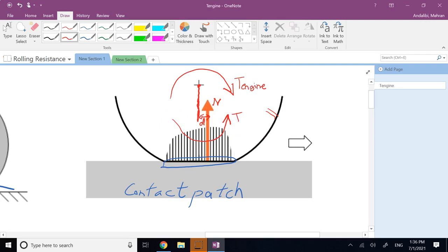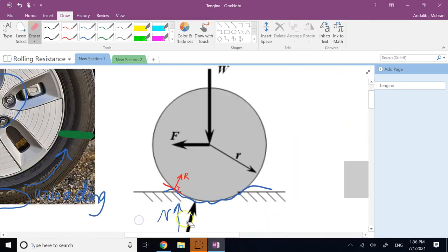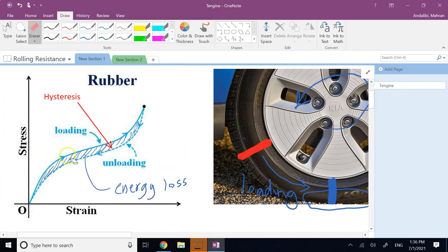This is the T of the rolling resistance, which is equal to N times d. You clearly see this torque is going to oppose the torque applied to the driving tires, and that's another way you can justify the waste in energy, right? It's an opposite torque. So whether you call it opposite torque, you call it opposite force, or you call it hysteresis, the matter of fact is when an object rolls on the floor of any type, there is always a resistance backwards which wastes the kinetic energy.